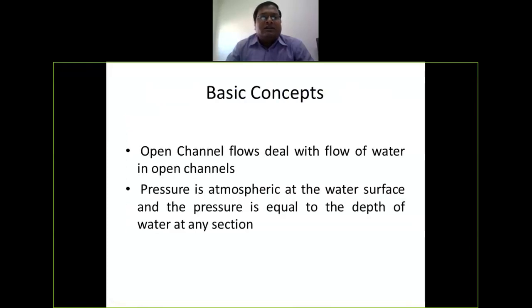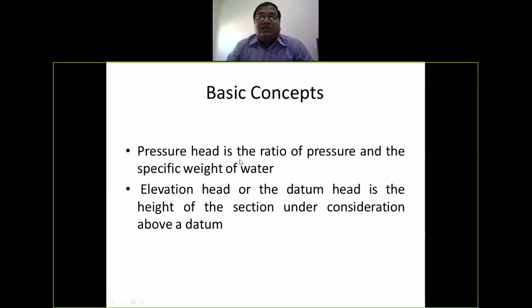Further, open channel flow deals with the flow of water in open channels. The pressure is atmospheric at the water surface, and the pressure is equal to the depth of water at any section, which is very important. Pressure head is the ratio of pressure to the specific weight of the water. Elevation head or datum head is the height of the section under consideration above the datum.